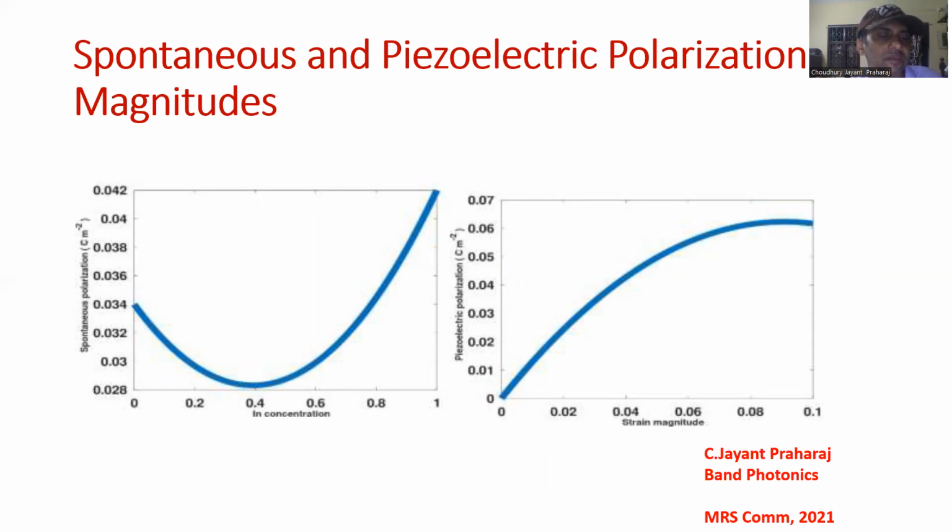You can see you can have some bowing dependence, and those all need to be entered into the device equations in order to predict and to understand the device characteristics and to understand the solar cell power conversion efficiencies, for example, as a function of the various kinds of device layer designs and device layer gradings that we use in these materials.